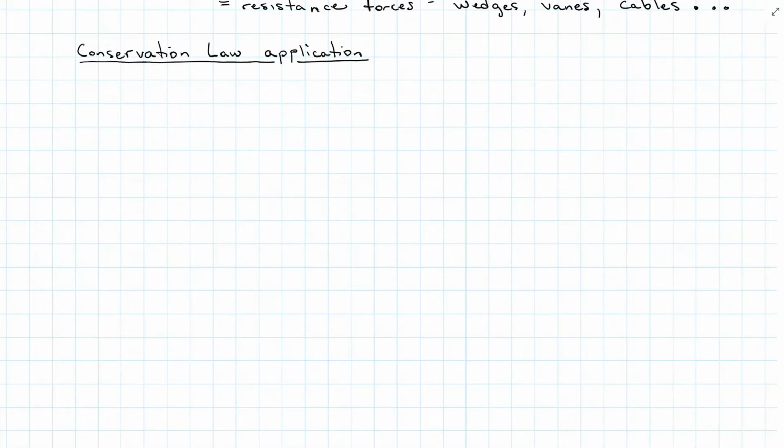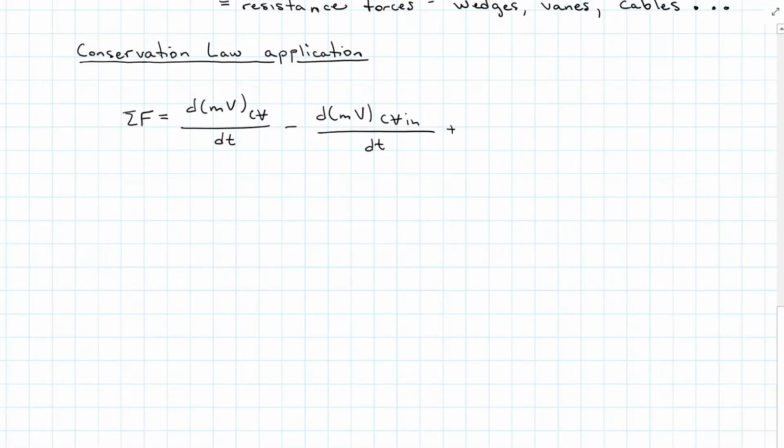We are talking about moving liquid, so let's talk about the conservation of momentum and adding it into the Eulerian Reynolds transport theorem. So we already have our forces due to the control volume situation, and we're going to subtract the rate that the momentum enters and add the rate the momentum exits. So we have our change in momentum that we discussed earlier, minus the incoming plus the outgoing. So we have a total sum of all external forces of this moving control volume situation.